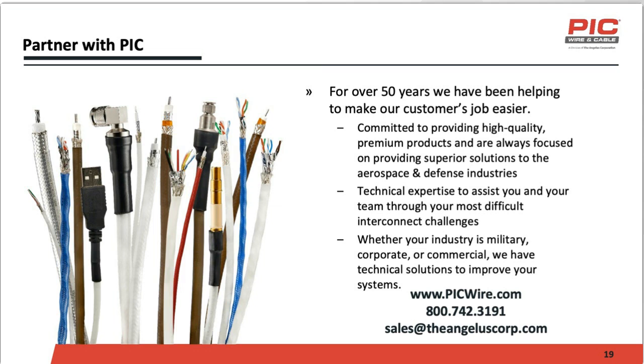Yeah, another great question. MACHFORCE takes roughly 12 minutes per port to terminate. And there's a lot of advantages that play into that termination time, including the fact that you utilize standard stripping and crimping tools to crimp on standard 22D contacts. So there's no soldering involved. And that makes field termination much easier, and it actually makes termination of connectors in the field and repair of connectors in the field possible.